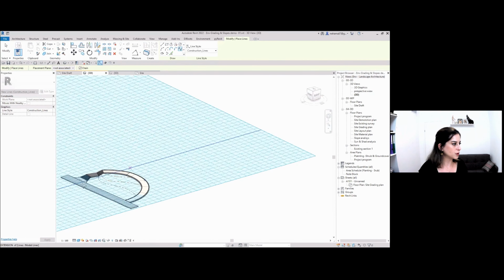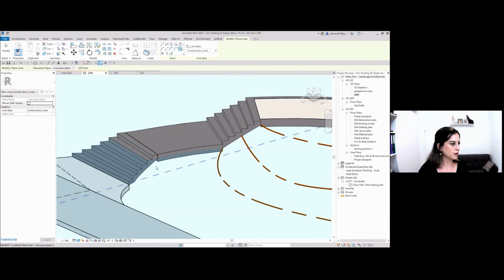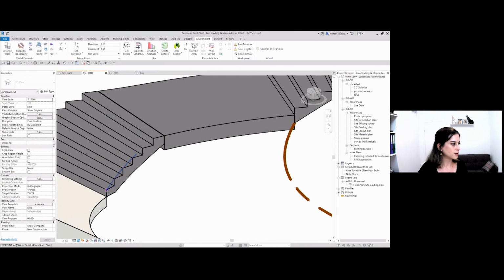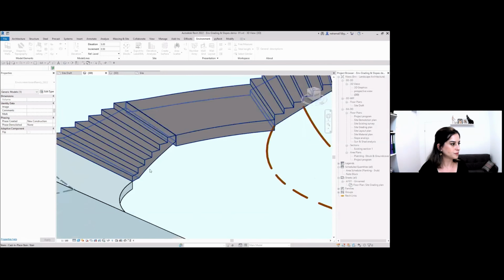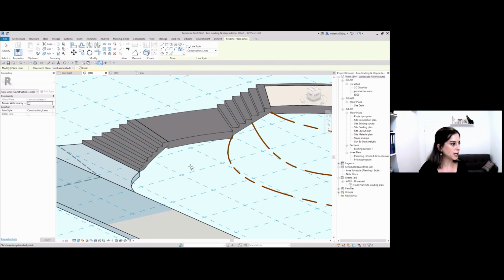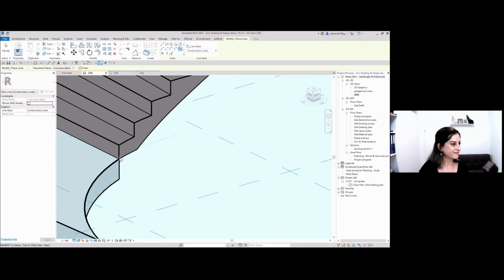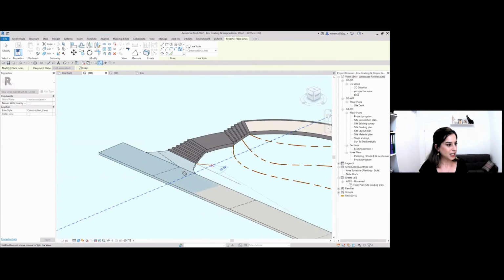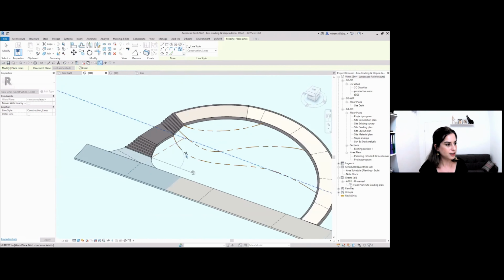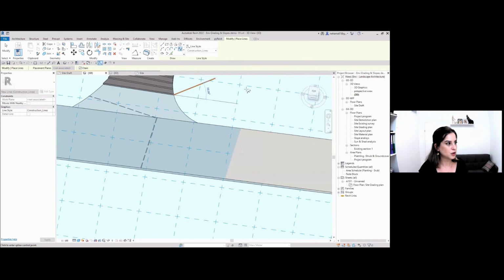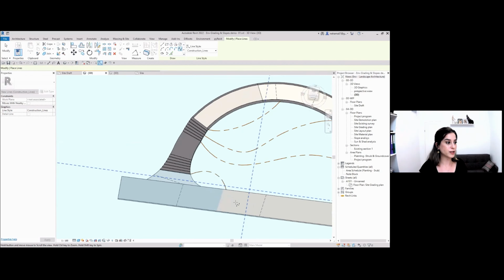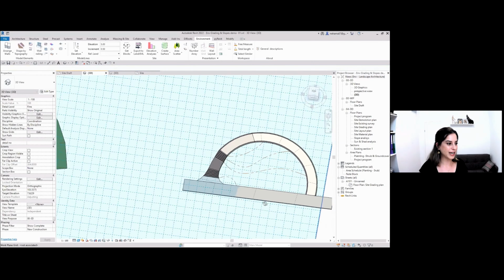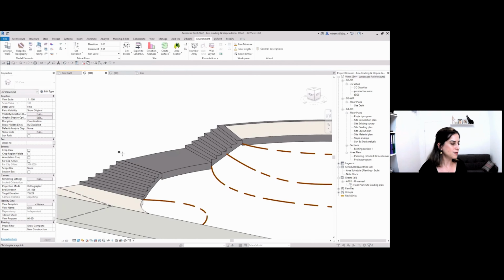And again, for the bottom of these stairs. So let's take 1, go to the spline tool, and let's connect it. 1 second, 1, 2. And you know what, with your permission, I'm just going to do it one more time so we will really get this beautiful result I want you to see.